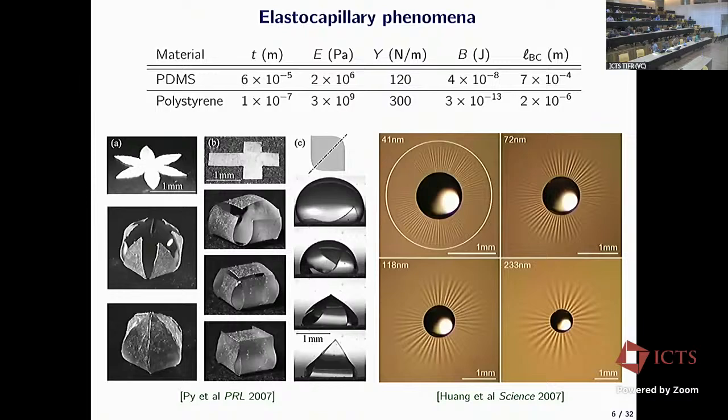So the basics of wrinkling are very simple. It's a kind of Euler buckling. We have discussed the stretching modulus. The stretching modulus tells you how difficult it is to stretch or compress a plate. So stretch or compress, okay, this is very difficult. The thing is that plates do not respond the same way under traction and compression. Under compression, you have another mode of response that is possible, which is just buckling.